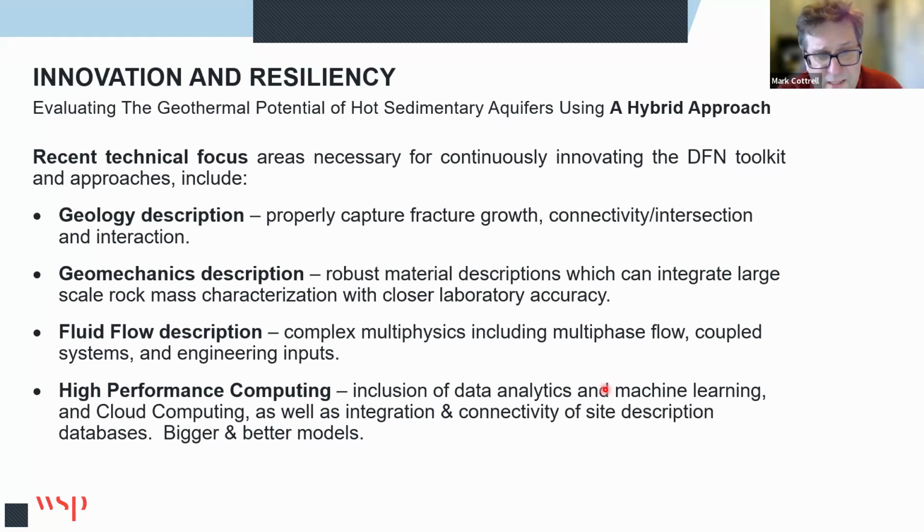That in turn is supplemented by geomechanical descriptions. Whilst we're able to characterize intact rock properties in a laboratory, we cannot do those kinds of things for the rock mass. We have neither the means nor the capability to actually transfer large volumes of rock that have both intact components and discontinuity components into the laboratory to characterize them as a rock mass.